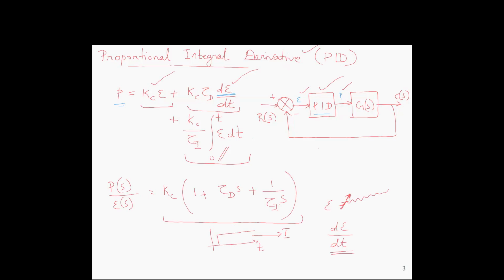So it is based on the slope of the error at that particular time instant. Therefore, a noisy error signal or a rapidly changing error signal will cause a large derivative response. In such situations, we need to avoid the derivative control. So if the error is very noisy, we need to avoid derivative control.